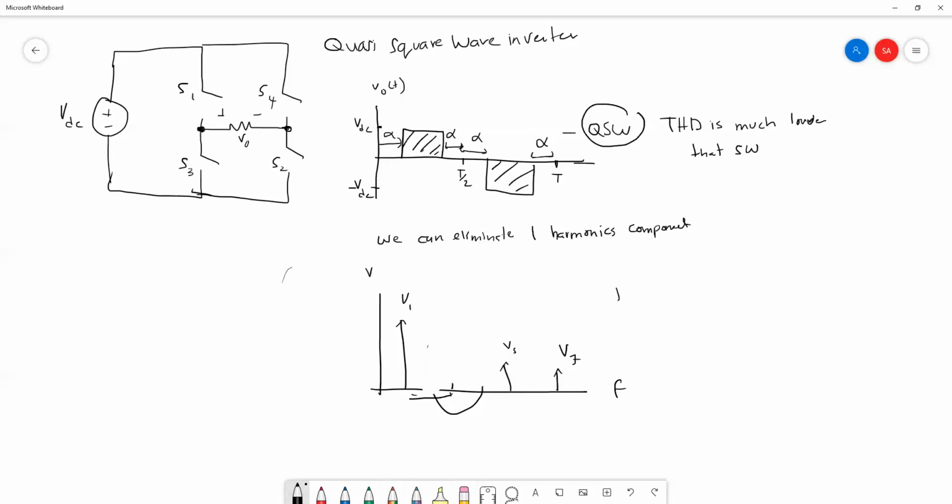It is beneficial if we can eliminate this third harmonic, because definitely the THD will be lower, and at the same time, as you can see here, the cut-off frequency when applying a low-pass filter can be made much larger compared to if we didn't eliminate the third harmonic. Before, when we had this third harmonic here, our cutoff frequency may be here, but when we eliminate the third harmonic, we can widen the low pass filter cutoff frequency more than the original cutoff frequency.